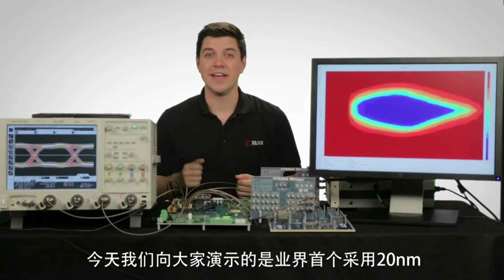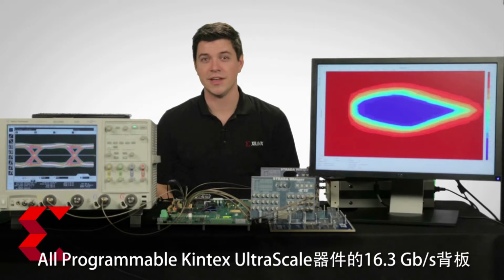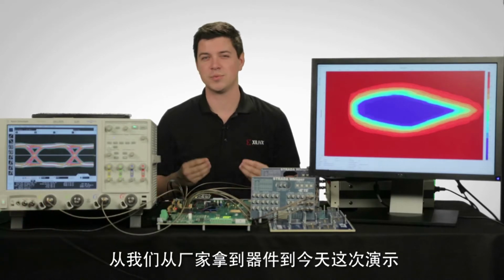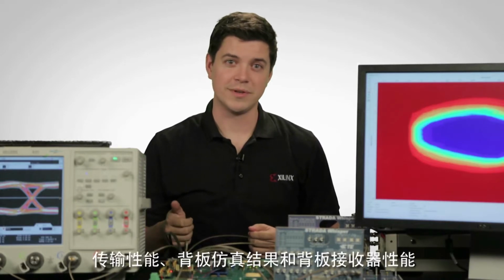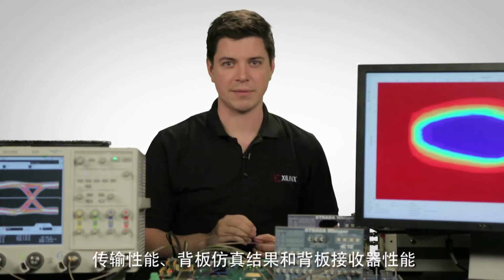Today we are showing you the industry's first 16.3 gigabit per second backplane demonstration featuring the 20nm all-programmable Kintex UltraScale device. We're able to show you this demonstration just weeks after getting silicon into the factory. The demo consists of three elements: transmit performance, backplane simulation results, and receiver performance over that same backplane.